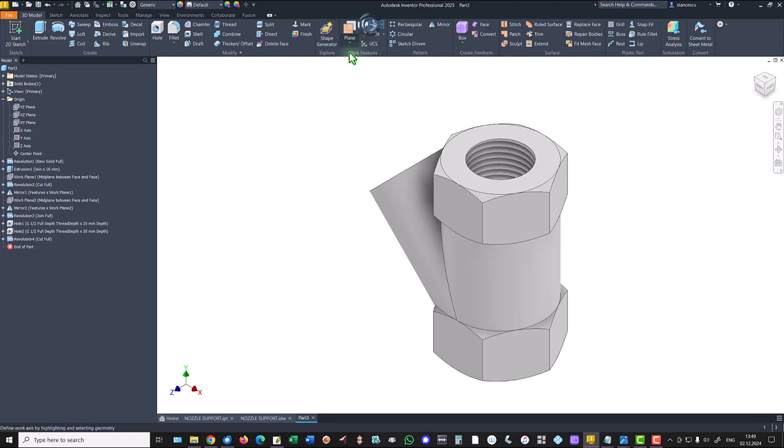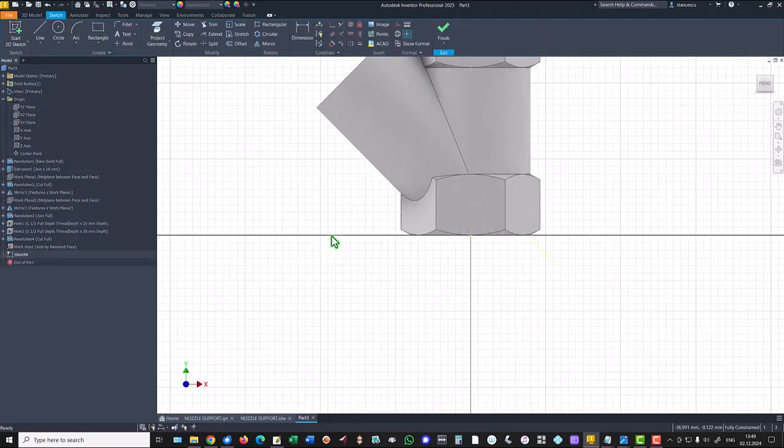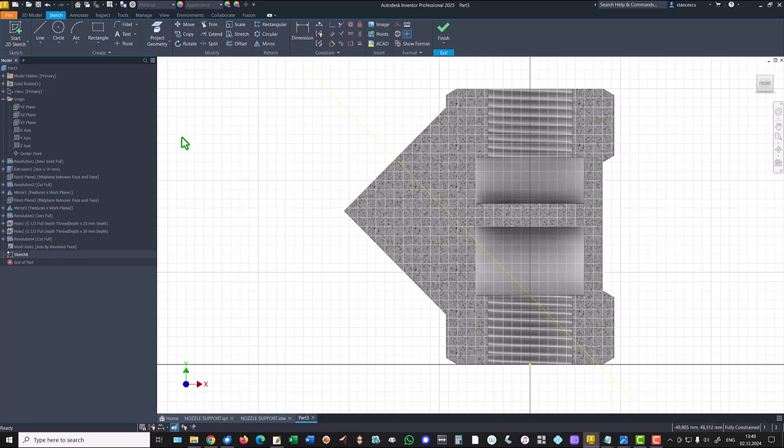Firstly, we create an axis. This is the axis, you see. Then in the plane XY, F7 and home, we project this axis and we hide the original axis. This is the center line. Then we use sloped rectangle starting from here, but let me project this.